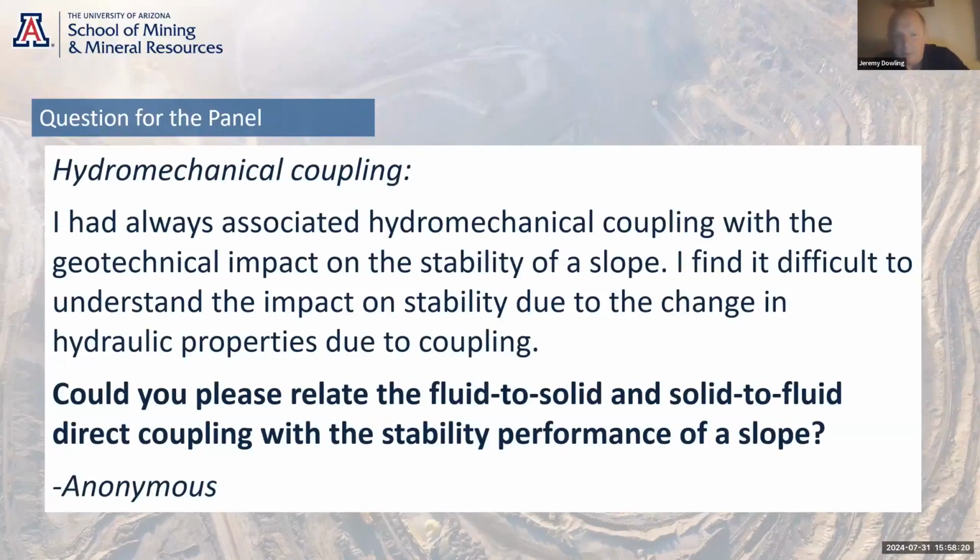And if there's any pore pressure in the rock, it will respond to that fracture dilation by a drop in the pore pressure, so the water in the rock will drop or expand into the new pore spaces, the new porosity that's created by the volumetric expansion.